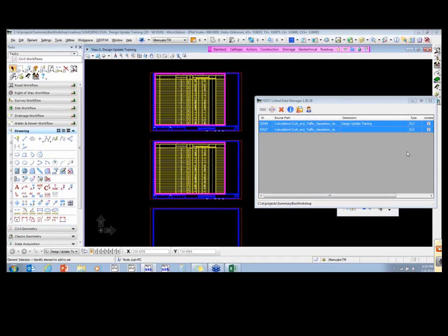It's not a mandatory requirement, but something to look at is maybe how long your plan sheet is, every 700 feet, or maybe make them roughly 700 to 1,000 feet. Something that is not huge, something that is constructible within a day.